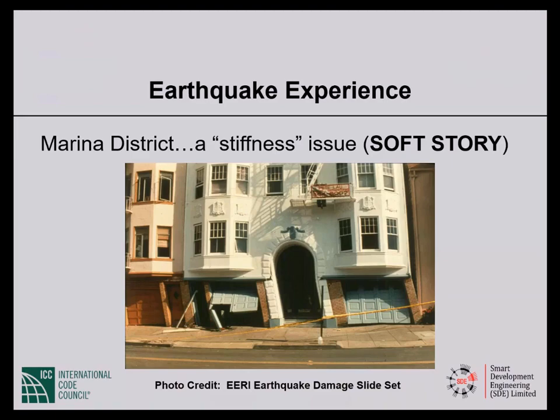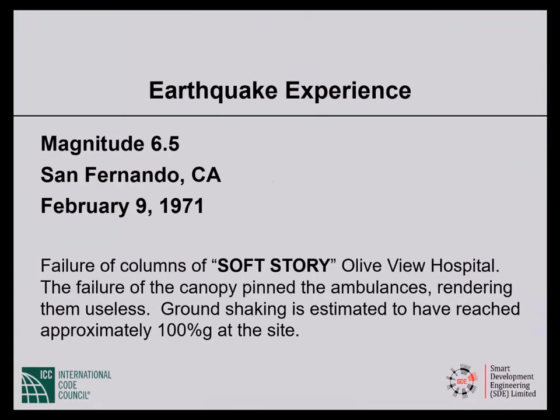Okay? This is a closer up view. So this garage was created, or this one, all the same. All the buildings had the same thing. This opening was cut in what used to be a shear wall, and now we have only the two pilasters or columns instead of a shear wall, and that is the reason why the buildings have a major problem.